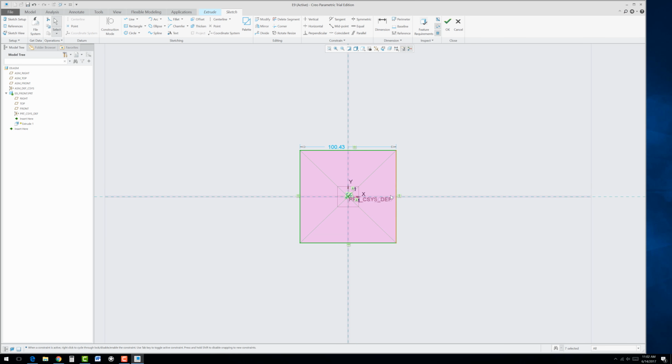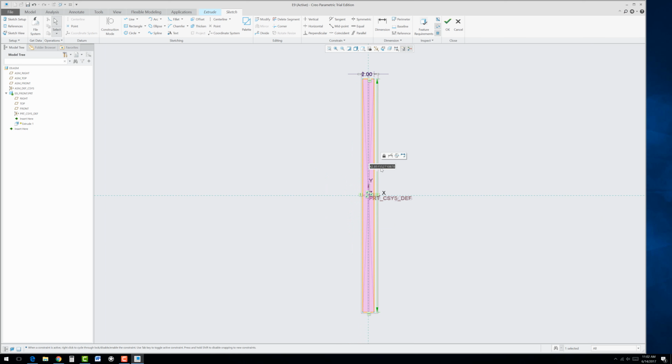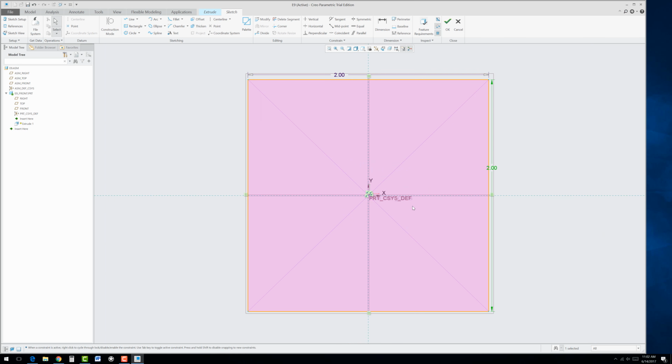Essentially here I don't see the equal symbols, but strangely enough, it's not giving me the second dimension. So I'm going to wipe that clean. Let's just start over again there. There we go. Okay. So basically, make sure you have both vertical and horizontal dimensions, and change those both to 2 by 2 to make a square.